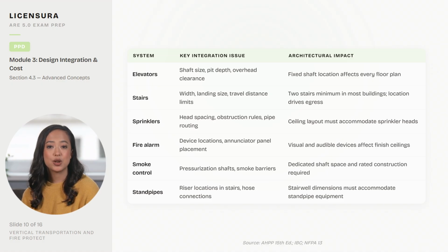The standard general warranty is 1 year per AIA A201. Extended warranties for roofing, waterproofing, and windows are specified separately by the architect. Warranty start date is typically substantial completion, not the installation date. Manufacturer warranties cover the product, while contractor warranties cover the installation quality.